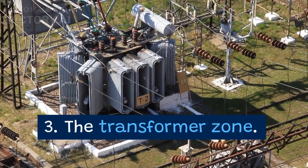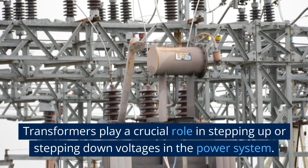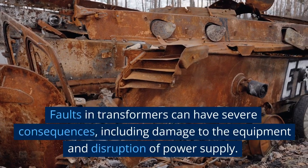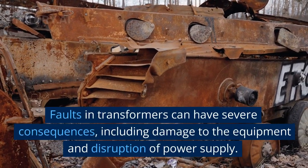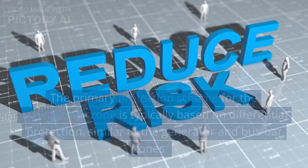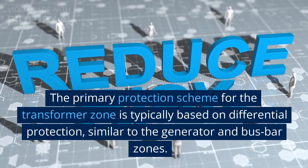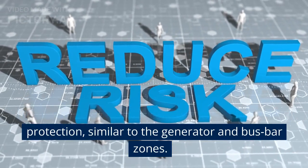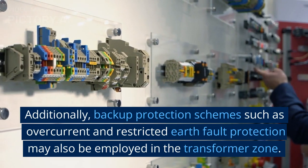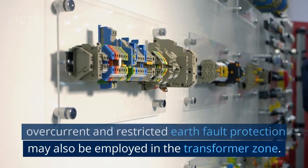Let's now explore the transformer zone. Transformers play a crucial role in stepping up or stepping down voltages in the power system. Faults in transformers can have severe consequences, including damage to the equipment and disruption of power supply. The primary protection scheme for the transformer zone is typically based on differential protection, similar to the generator and busbar zones. Additionally, backup protection schemes such as overcurrent and restricted earth fault protection may also be employed in the transformer zone.